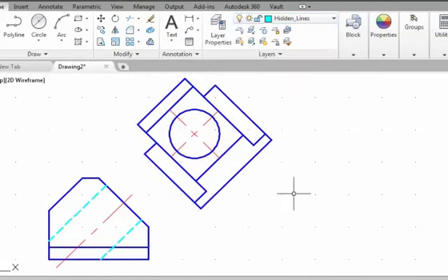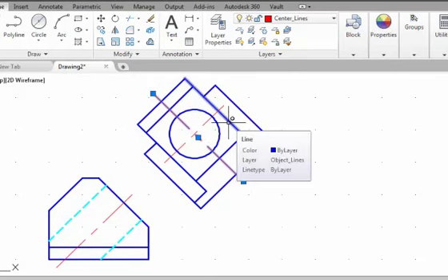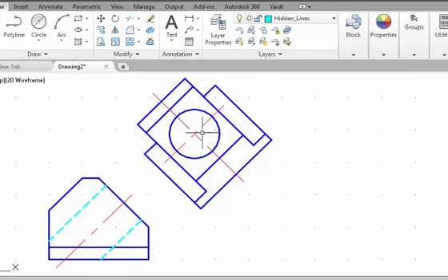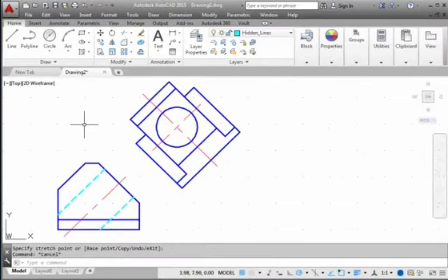I'm going to extend the center lines out a bit. According to the ANSI drafting standard, center lines should extend beyond the features about 1/4 of an inch. Although we do not need to actually measure the distance, we should try to make it roughly at that distance. Center lines can also be used to indicate symmetry. We have created the necessary views for the design.